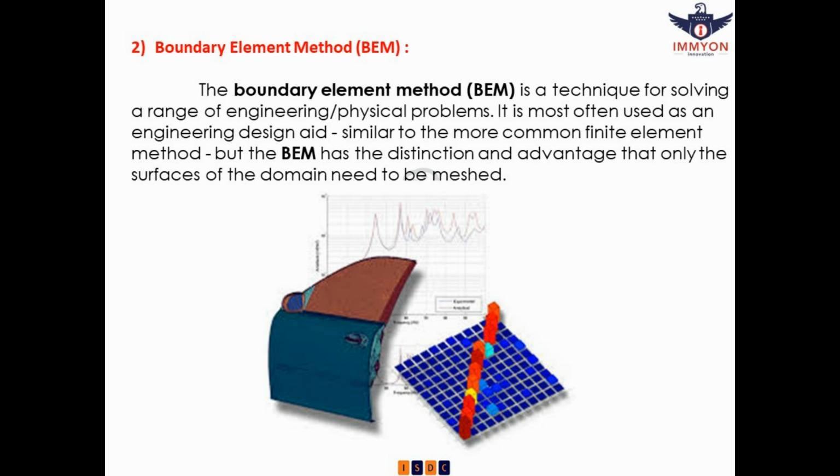2. Boundary element method, BEM. This is a very powerful and efficient technique to solve acoustics or NVH problems. Just like the finite element method, it also requires nodes and elements, but as the name suggests, it only considers the outer boundary of the domain. So when the problem is of a volume, only the outer surfaces are considered. If the domain is of an area, then only the outer periphery is considered. This way it reduces the dimensionality of the problem by a degree of 1 and thus solves the problem faster.